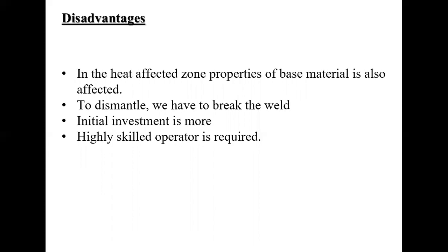Next point I'm going to discuss is that the initial investment is more. For every type of welding, we have to buy a setup, which is also a costly thing. Another important part is that a highly skilled operator is required. In case of arc welding or other welding, which is very risky, high skill is required for the operators.